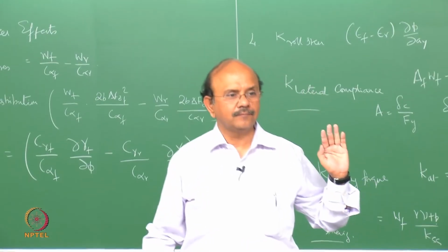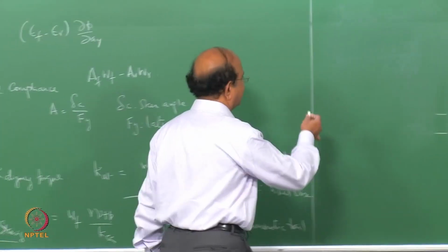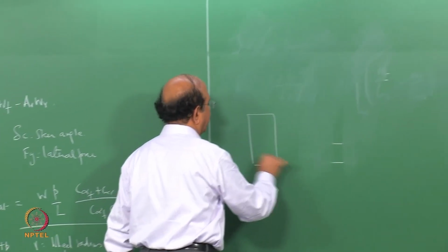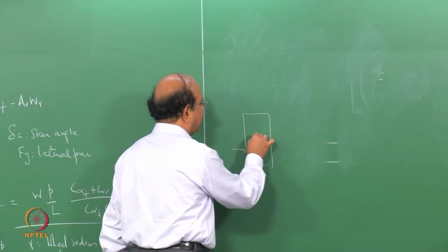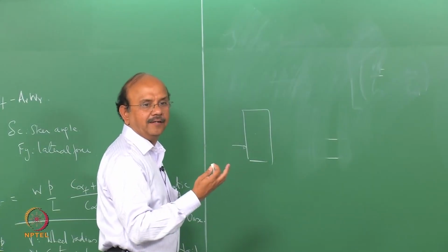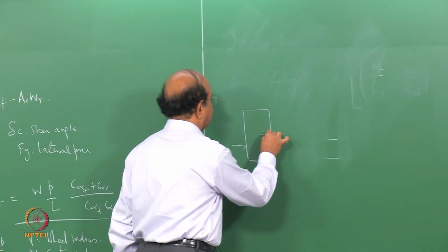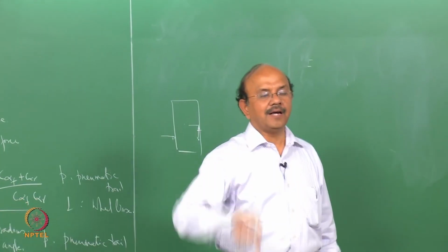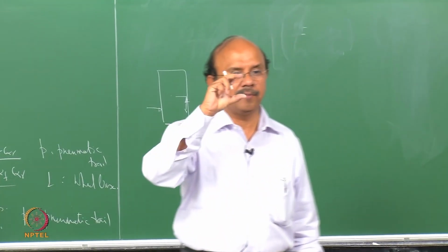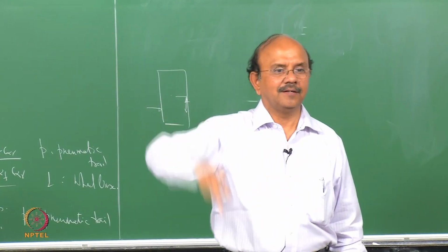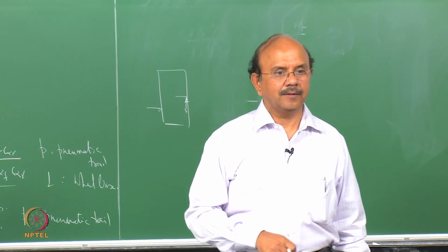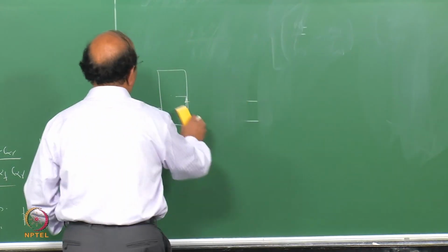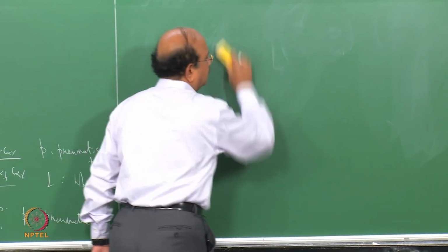Any questions? Yes. Pneumatic trail, we already saw that. The lateral force does not act at the center, it acts at the rear. That is the moment that's created, that distance at which this acts and gives the aligning torque. The force multiplied by pneumatic trail gives the aligning torque. Okay, so that's what we saw long ago as the pneumatic trail.